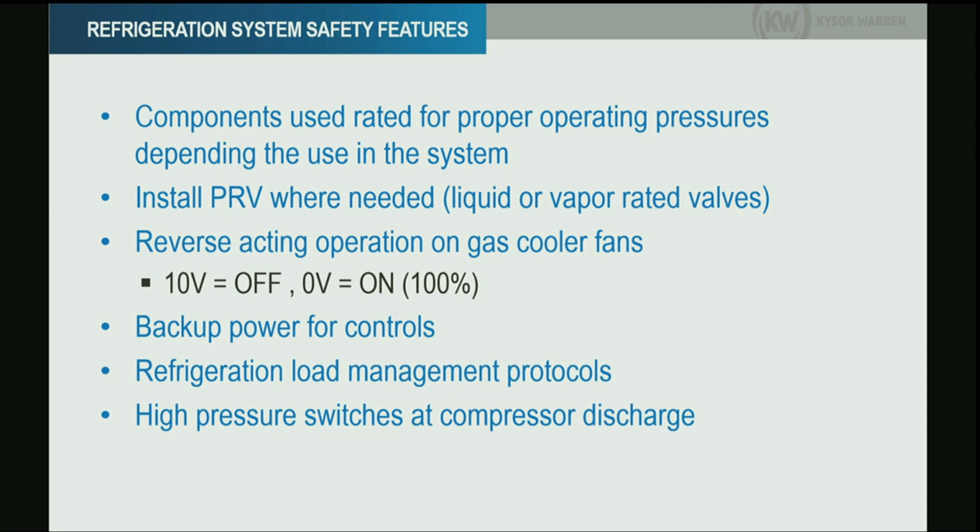Because it's common that you can lose the signal from your system. Even if you don't lose the power, you can lose the signal. And if you get 0 volts in the gas cooler, they will be running 100%. What happens there, you have excess capacity, things like that. But that will not shut down your system. If you have the 0 to 10, and you get 0, your fans will be off, and then you have high pressures, and the system shuts down. So that's an important thing to know.